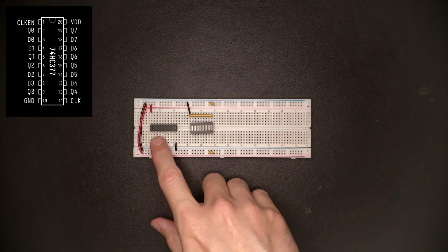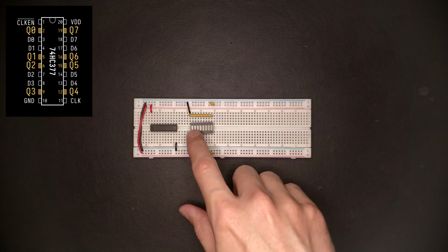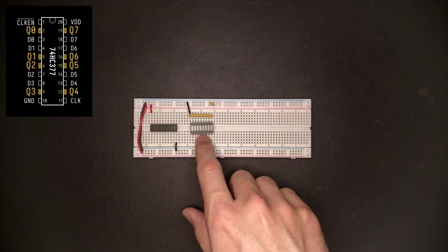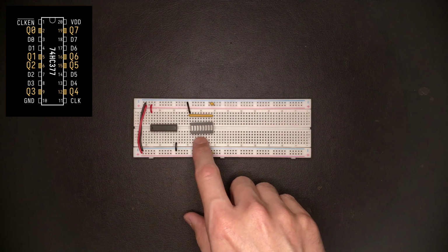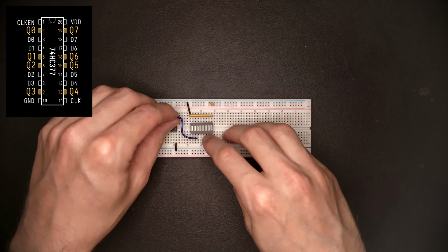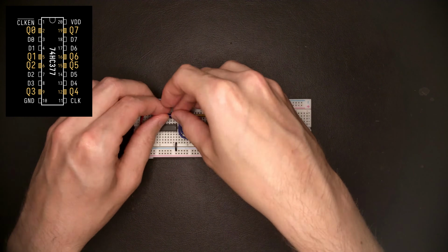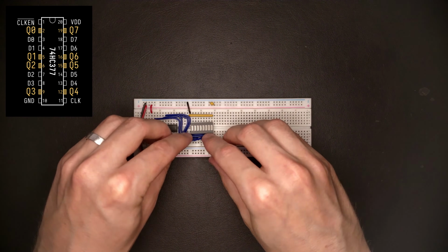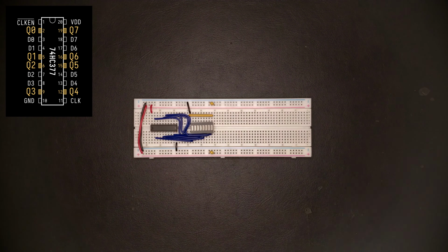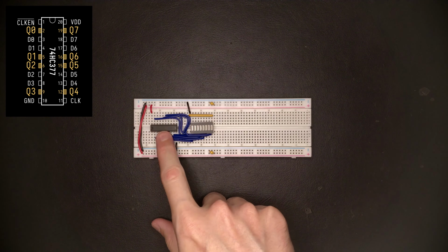Now we'll want to bring the data outputs of the register chip here over to the bar graph LEDs so we can actually display them. And this will be a good opportunity to have all the 8 bits lined up such that we can bring them over to the other chips on the breadboard later on. Okay, that should be all the LEDs hooked up to the outputs of the register here.